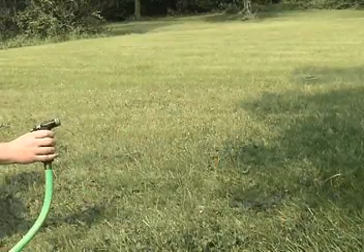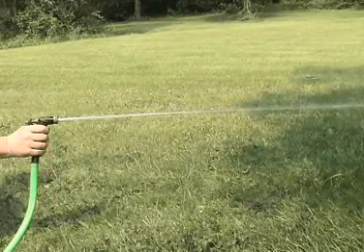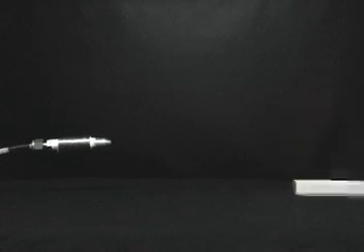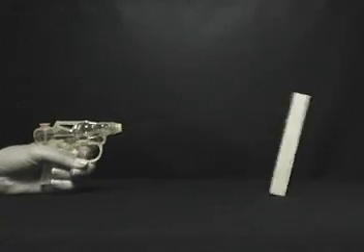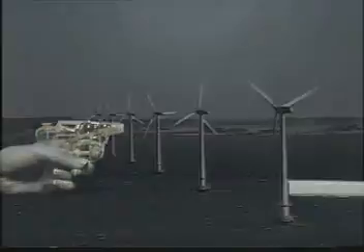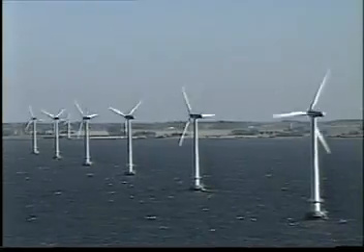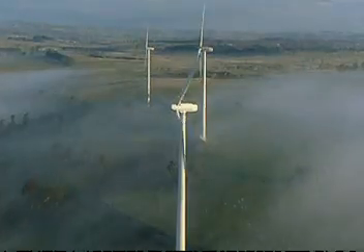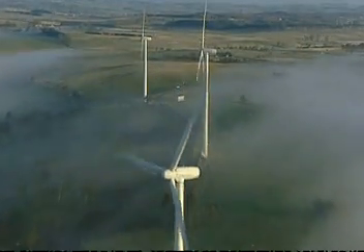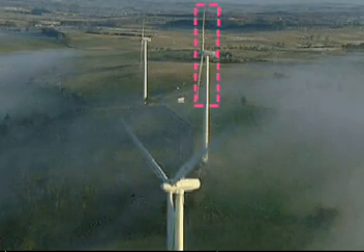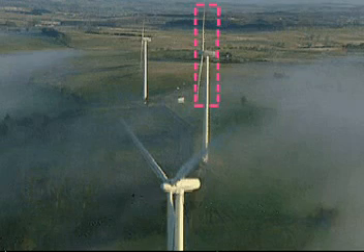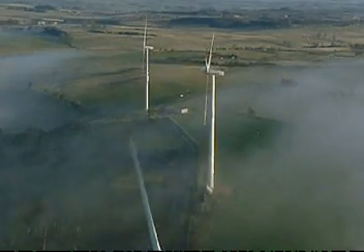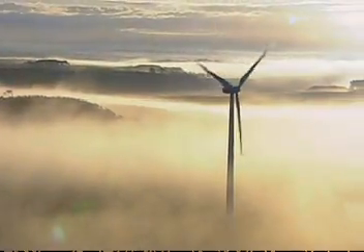The momentum flux of a fluid is the product of its velocity and mass flow rate. Thus we can get about the same momentum from a high-speed jet of a light fluid like air as from a slower jet of a dense fluid like water. There are many interesting and useful examples of such momentum control volume analyses. Here's one showing a control volume for a wind turbine. If we know the wind speed and power output, we can analyze the forces on the wind turbine and determine its efficiency.